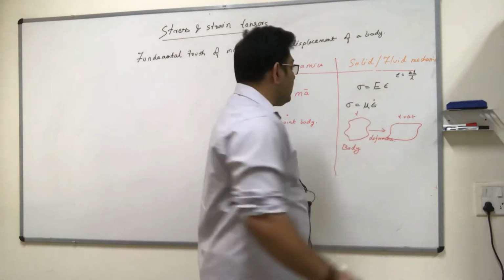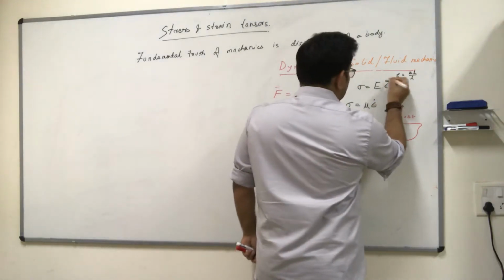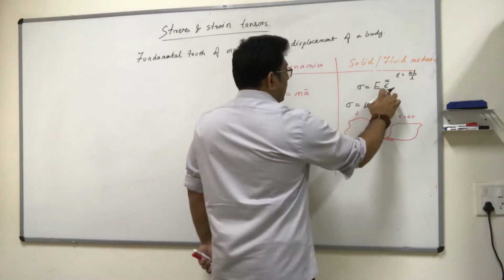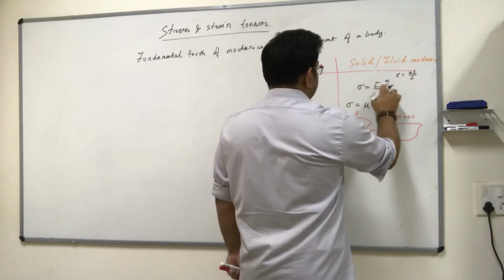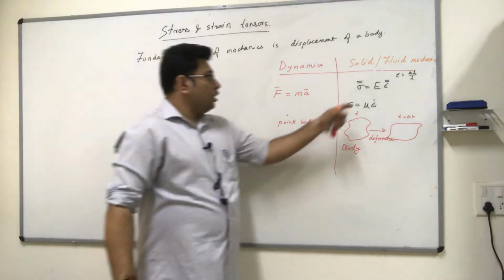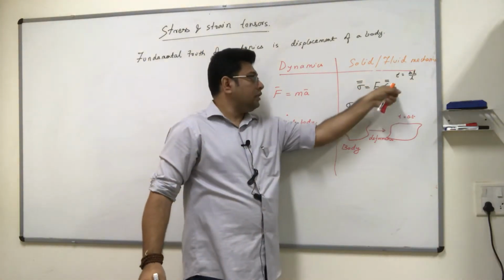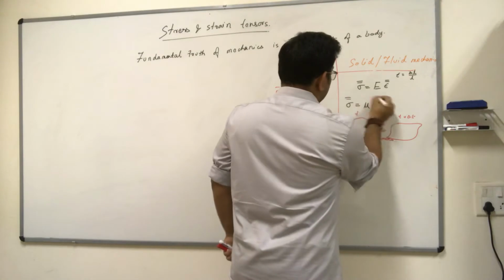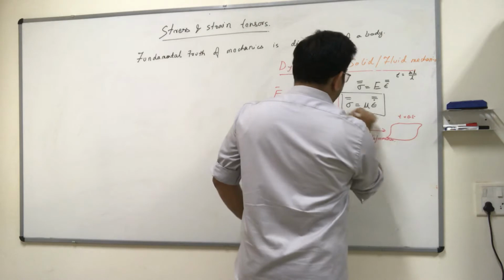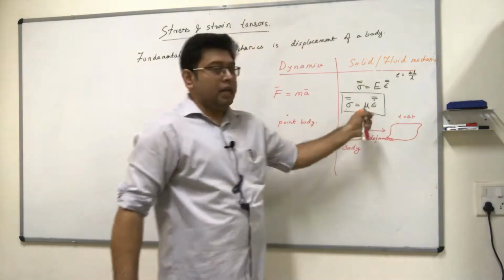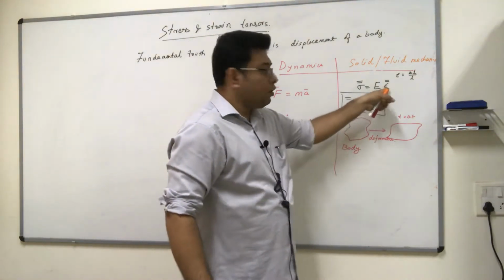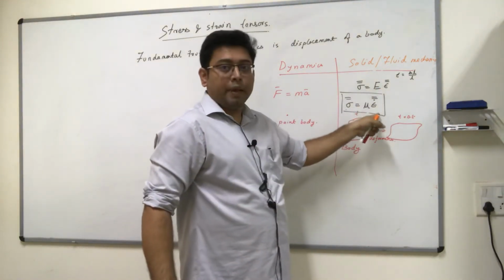Well, no. We'll see that strain is a tensor. Actually, we will not look at strain, we will look at the strain rate. But in solid mechanics, you come up with strain, which is a tensor, and this quantity equivalently now also becomes a tensor. So this is your stress and this is your strain. In fluid mechanics, we will be looking at strain rate. So we are interested in this form. By the way, this is also a very simplified form. Okay, this is not the exactly correct form, but I'm writing it for a particular reason, because I wanted to draw the analogy with solid mechanics.